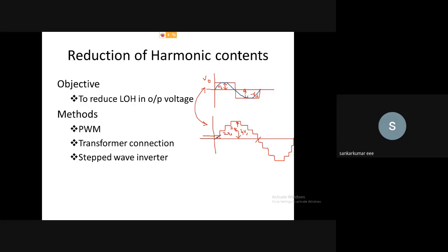And here also we have to take the sine waveform, that is your fundamental waveform. So this is your fundamental, that is the sine waveform. When we are comparing this, the multi-level inverter output waveform is approaching more sinusoidal when compared to this two-step or the square waveform.